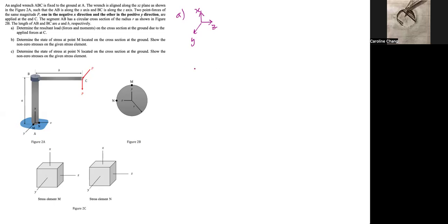external loads and forces. For instance, let's review a little bit of theory. So for internal reactions, we define things as positive when they're in tension. And notice that even though this arrow is pointing to the left, in the context of this portion of the beam, it is positive because that segment of the beam is in tension. And negative will be when the internal reaction is in compression. And this is important when analyzing this whole structure over here.